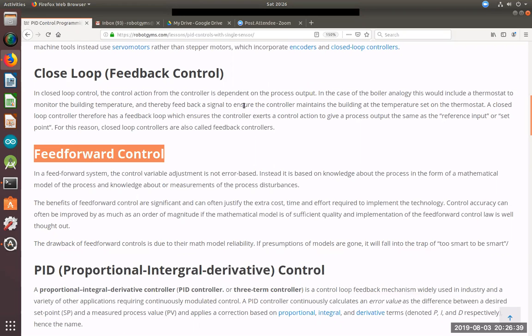So if you have a second term, look at the derivative of your speed change. So you find out your error reduce really, really fast. It's not constantly reduce really fast. That means you should slow down, right? So that means when you turn at a 45 degree point, you should not use full power. Okay? Or you should not use 0.5 at all.